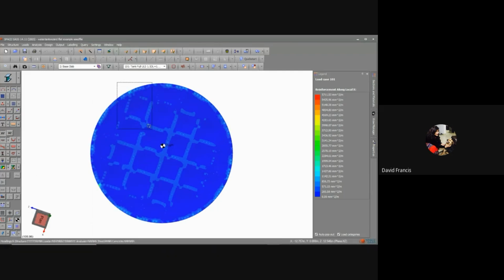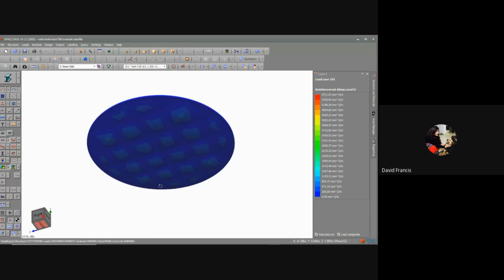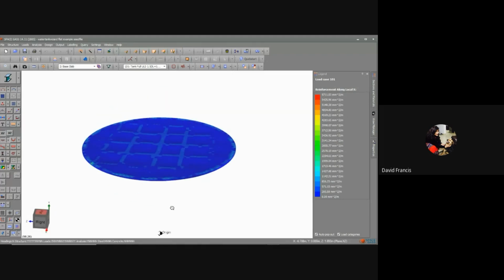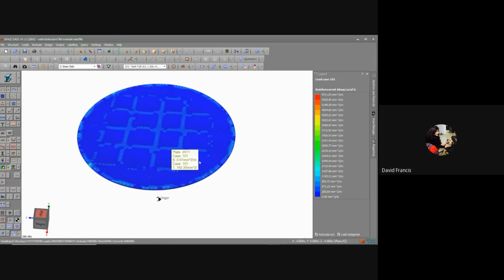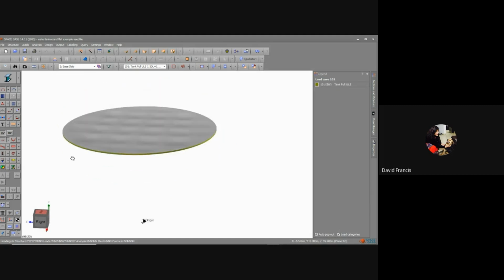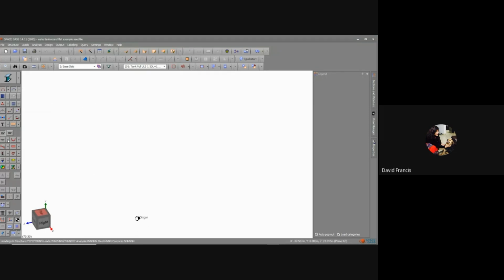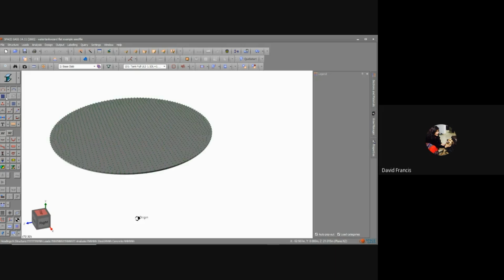So you've got your bottom and your top. If I move over, you'll see what it's showing me. It's showing me the top and bottom steel, minimum requirements for that design. Okay. The other thing I can do if I want to get flashier is I'm going to turn the meshing on. Deflected shape I'm going to turn off. Turn the meshing on.